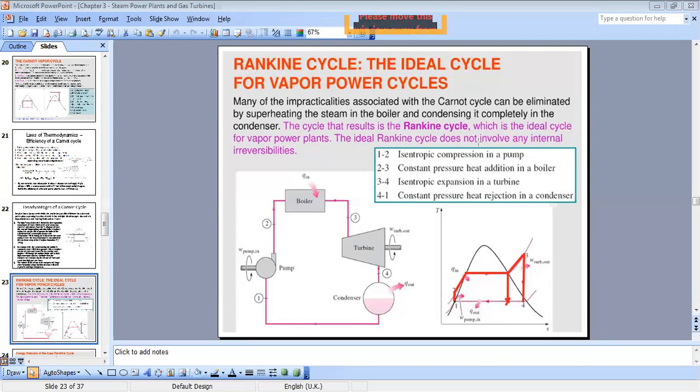Okay, so this is the Rankine cycle. The Rankine cycle has as its purpose to protect my pump and to protect my turbine. These are the modifications done. Point 1 is just at the saturated liquid zone, and the point of exit of the turbine is very close to a quality of 1.